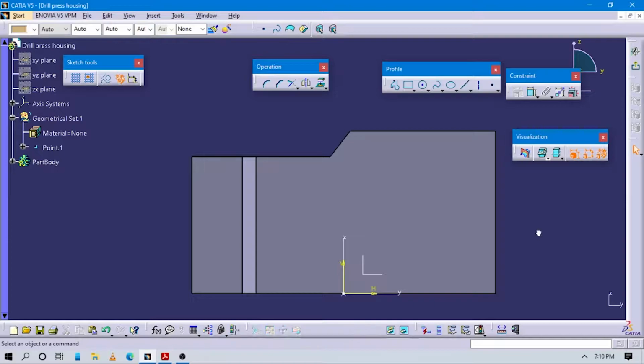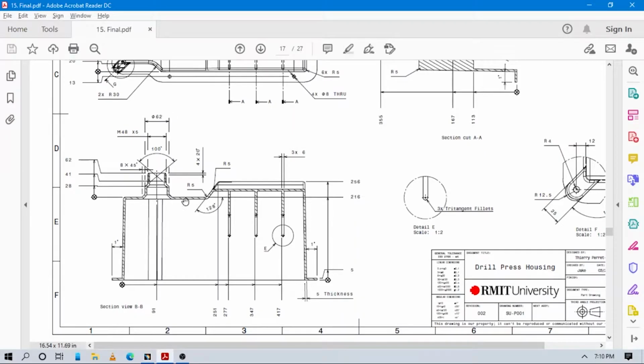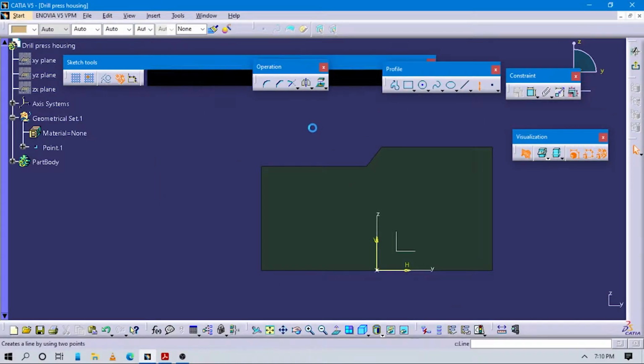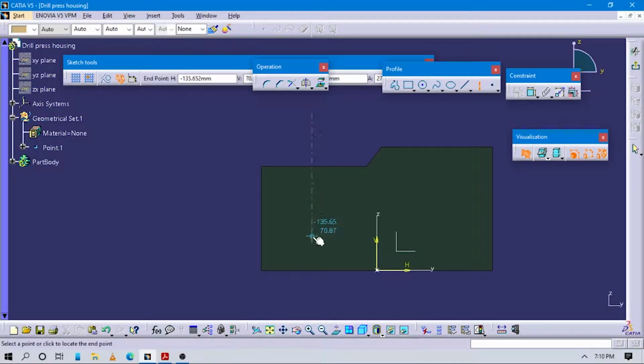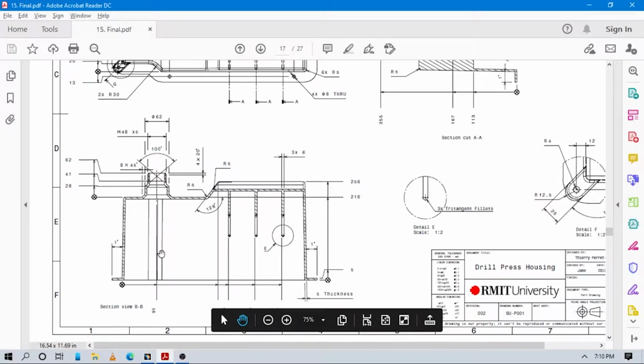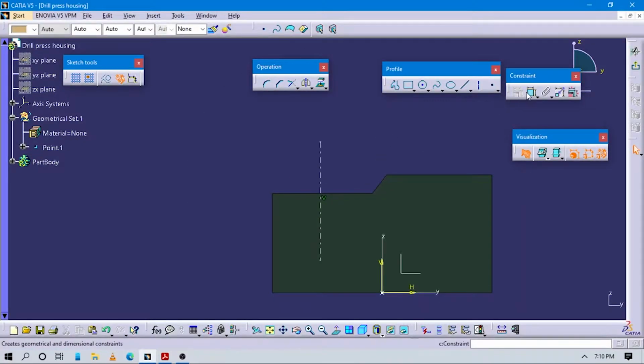And to get proper dimension, select this cut part by sketch plane from this visualization tab, and now create this part perfectly. So before creating this, create one axis here, and this axis is present from here. It is, you can see, I think it is 91, and this to this distance is given as 91.